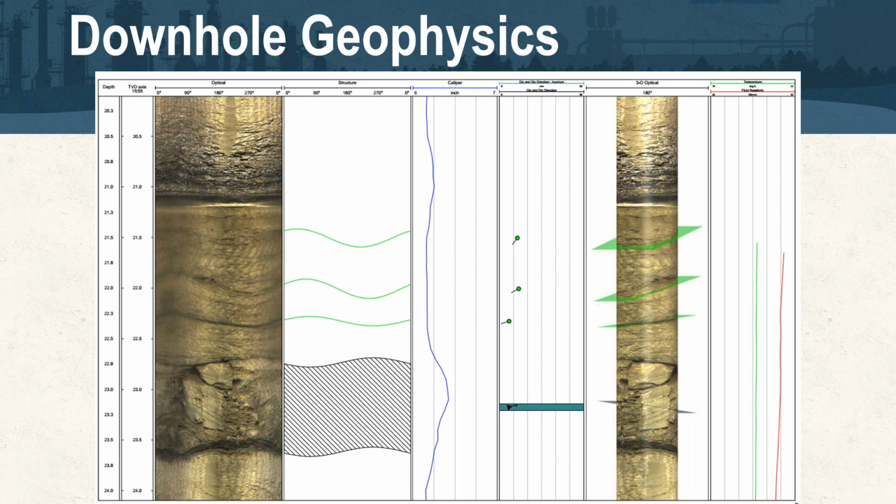Probably first and foremost, Bill just talked about the different coring you can physically do. You can also take different sonic cores. I know some areas of the country where that's preferential based upon geology, cost, and speed. As I mentioned in an earlier slide, in terms of putting in a borehole that I'm going to use for characterization and injection, personal preference is air rotary. In some areas where you're drilling in rock that's a bit softer, a bit less competent, blowing out that hole when you're finished is really important, trying to get a nice clean face on the inside of that boring.